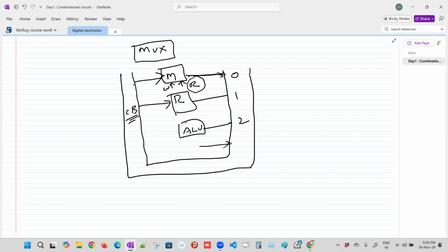Now let's say to put these contents onto the bus, 5 nanoseconds are required. After 5 nanoseconds only, in the instruction, whatever the memory has put should come to the ALU, let us say. So at that time, after 5 nanoseconds, the select lines will now be enabled as 2. And the ALU again has several units inside: arithmetic units and logic units.